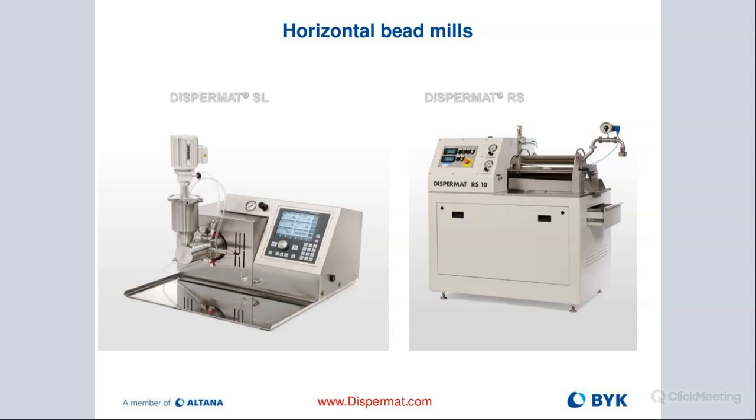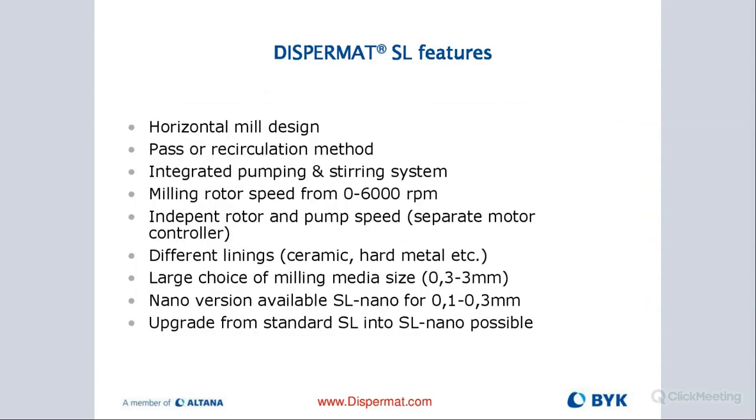So depending on how small I want to go, I can circulate the mill base for a long time to go from, let's say, 1 micron all the way down to 100 nanometers. I may have to swap out the beads in the process to make the beads also smaller, but that will be the way that this mill functions, and the same concept on production scale.